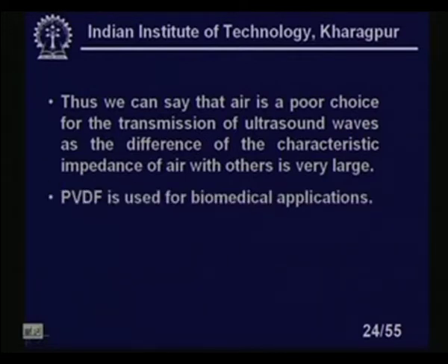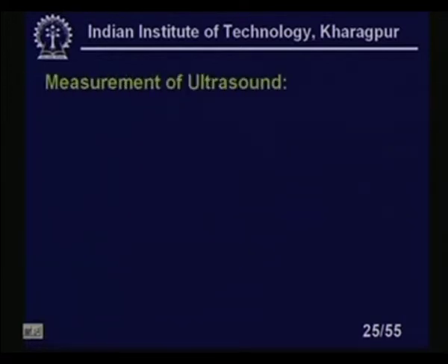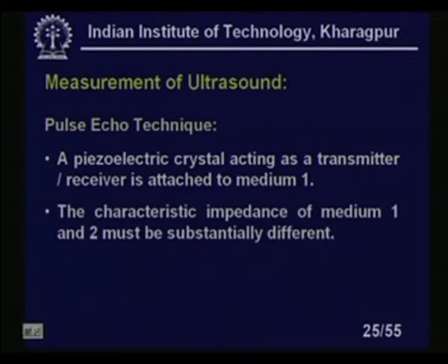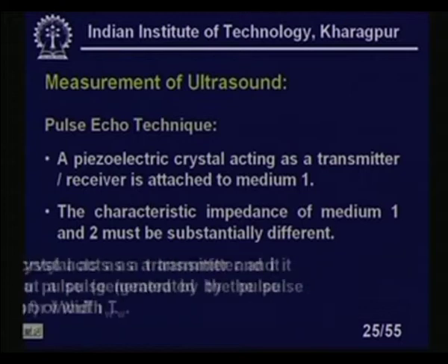PVDF is a polymer, actually used for biomedical applications. So, measurement of ultrasound, pulse echo technique: a piezoelectric crystal acting as a transmitter-receiver is attached to medium 1, I will show the diagram. The characteristic impedance of medium 1 and 2 must be substantially different, otherwise the wave cannot be reflected.